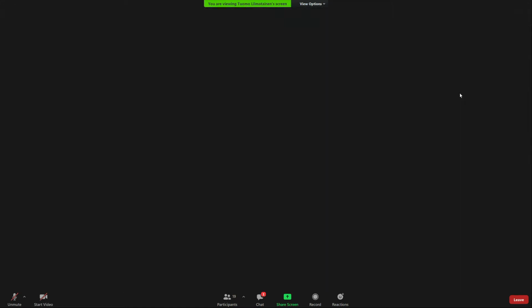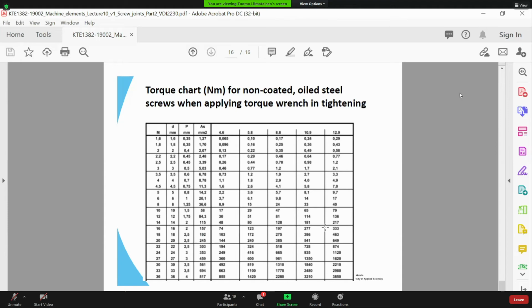So it is really important in a bolt joint where you have to control the preloading that you control the friction, because that has a huge effect on the realized preloading in the structure. So that was the meaning of this exercise.